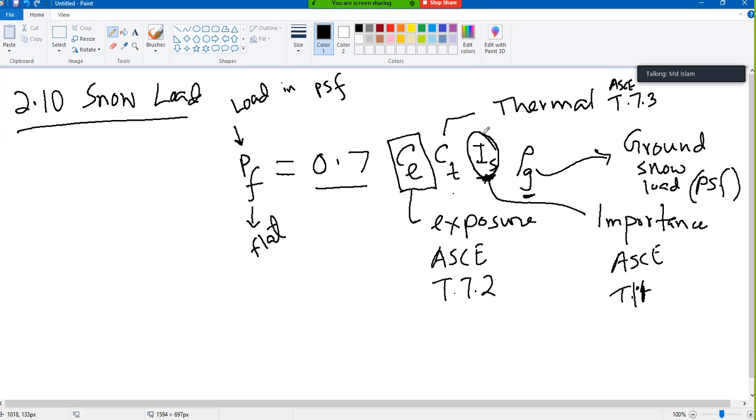Normal building or agricultural storage or similar, or even in your ranch where there are some animals, 0.8. Normal building of school type, school building, gallery, stadium, assembly, this kind of building, lot of people, 1.1. Hospital, clinic, this kind of building, 1.2. So the story about Is is done.